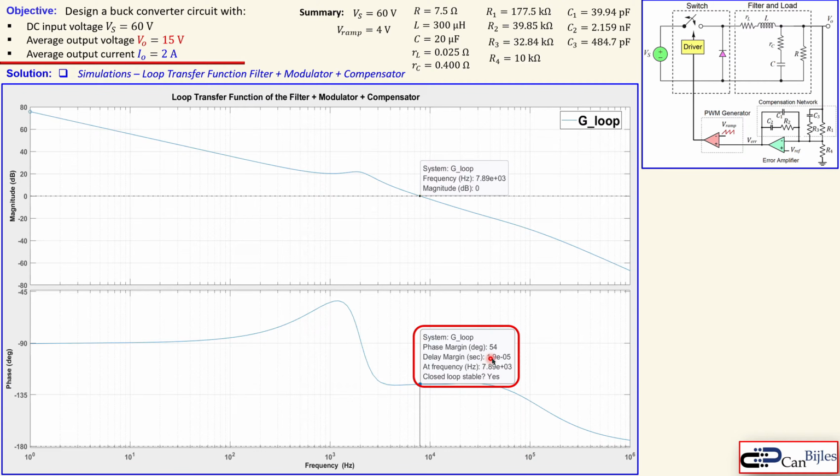So there's not much of a difference compared to the first case. And also the unity gain frequency or the crossover frequency is not anymore 10 kilohertz, but let's say 7.9 kilohertz. So we go down by 2.1 kilohertz. That is perfectly possible because we also made some approximations in our calculations by assuming that some values were larger than the others. Let's say we said R1 is much larger than R3, which is not true. It is larger, but not a lot larger. So there are some errors we also made before we started the calculations.